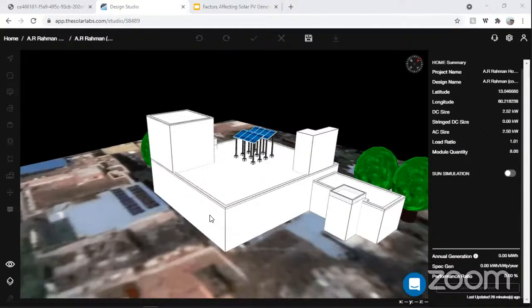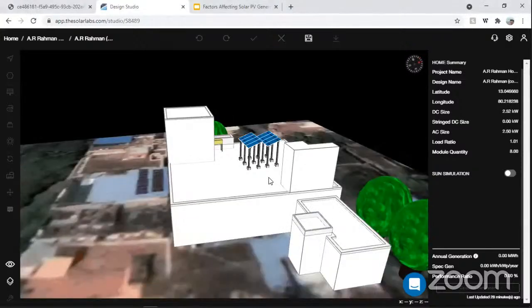Yes. So, Mr. Priyanshu, for that, basically, we are using ACDBs and DCDBs, right? Our SPDs are embedded in our ACDBs and DCDBs. The basic concept is that whenever our panels create the DC power and it is transferred to my inverter, in order to protect my inverter, we are using a DCDB, right? That is your direct current distribution box in which we have the SPDs installed.